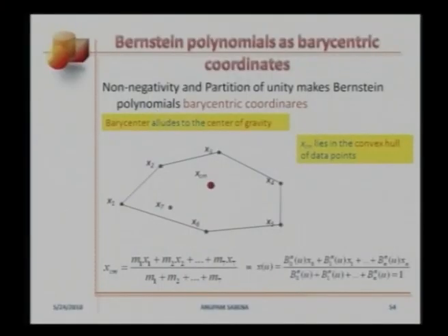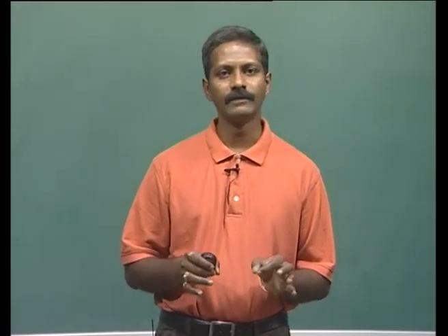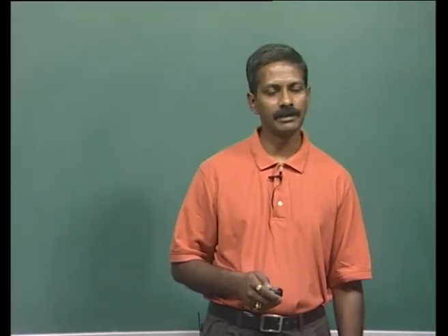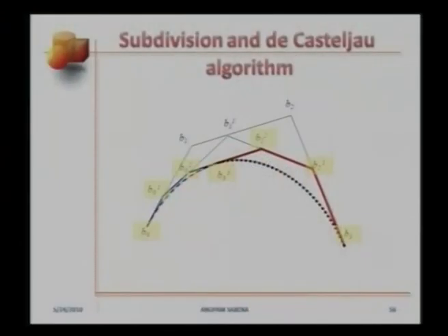An important thing, any point on the Bezier curve is bound to lie within the convex hull defined by the corresponding design points, and this was the essence behind the Bezier curve models. We also studied subdivision, where given a Bezier segment, we could subdivide that in two different Bezier segments of the same degree without changing the shape of the segment by itself.